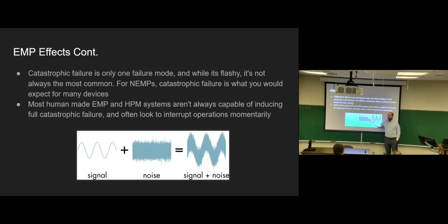It's a bunch of really weird noise, unexpected, hard to handle, but imagine it would be far larger magnitude to the point where you almost wouldn't even be able to discern that there's a sinusoid under here anymore. When you do that, the computer can't read it anymore. So EMPs and high power microwaves let you jam out at the hardware level instead of at the receiver or the software level. So you're not battling algorithms anymore, you're just battling physics. So in a lot of instances, this is easier to do and more useful to do than actually attempting to intelligently jam something like a radio.